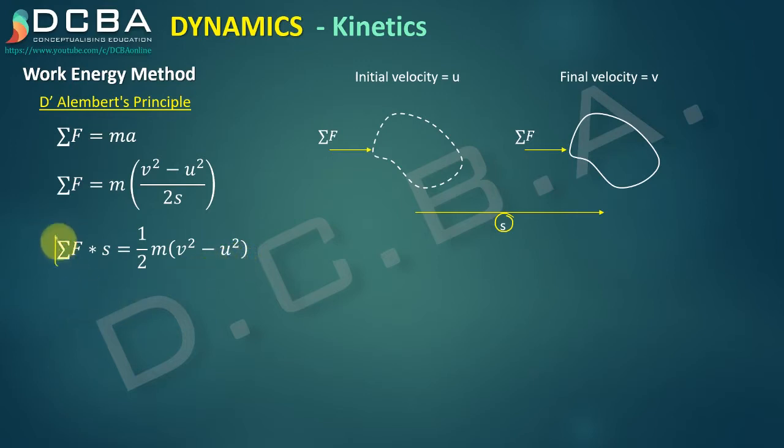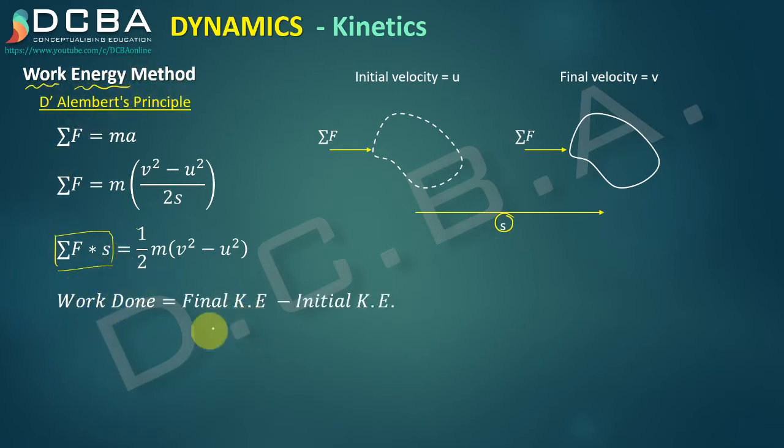right? So this term which is there, this is force into your displacement. Force into your displacement is nothing but the work, right? And the units are Newton meters, or the units of force and the units of displacement. And on the right hand side what you see is half mv square minus half mu square. So this is nothing but the final kinetic energy minus the initial kinetic energy, and hence this is called the work energy method. Okay, so work done is equal to final kinetic energy minus initial kinetic energy.